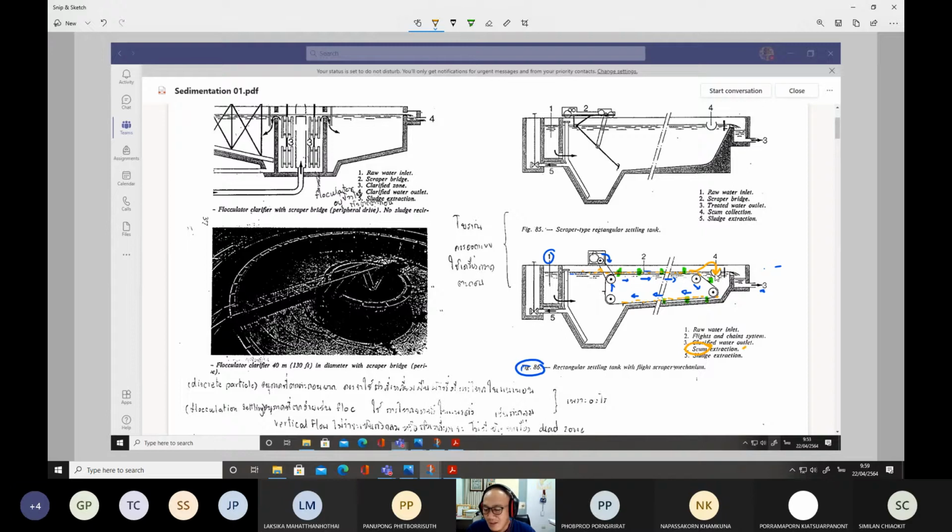So this is the equipment we usually call the scum extraction. Basically, it's a kind of trash. We put it here just to collect the floating scum in case it goes up instead of going down by gravity. So this is how the rectangular settling tanks work.